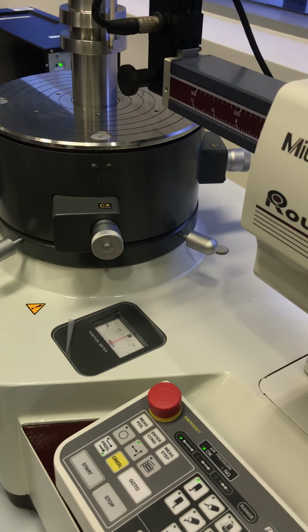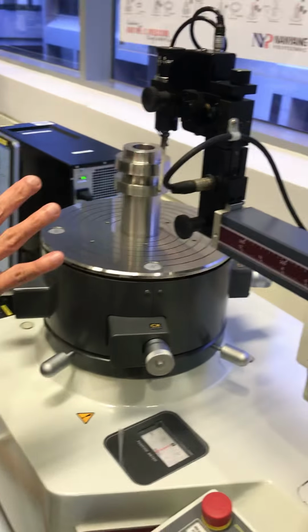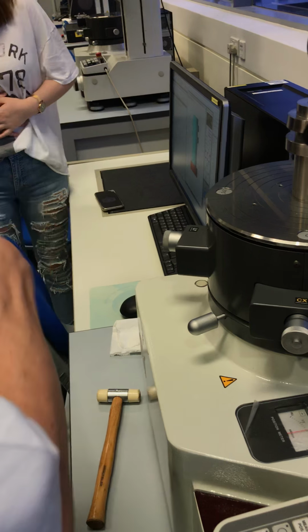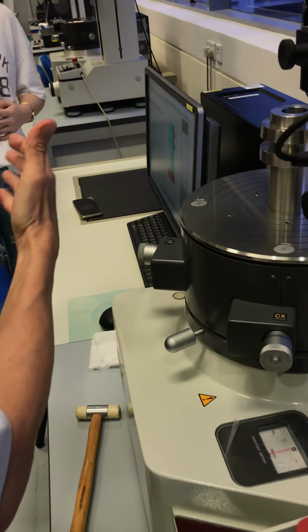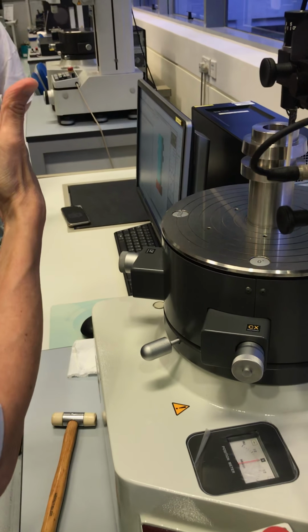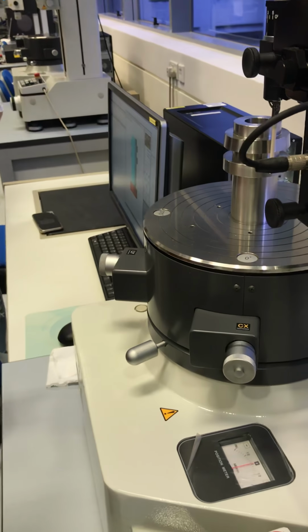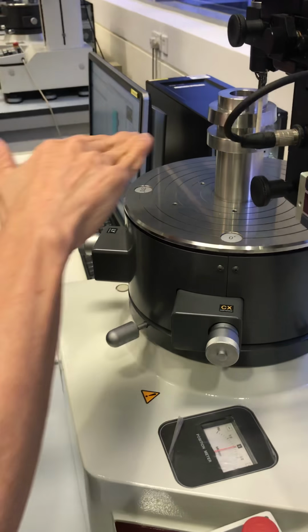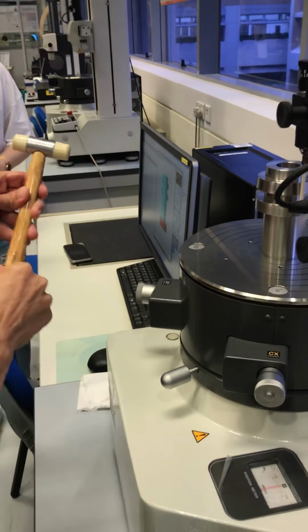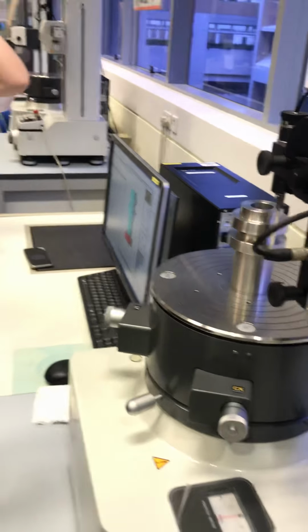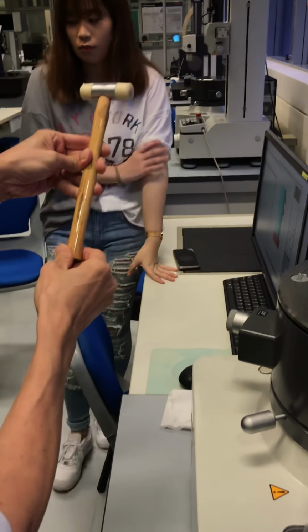Okay, this rough alignment, this is called a rough alignment. Then for very fine alignment at higher magnification, you need the software to help you do the alignment. The alignment is also based on the tilting. We only check the circle, but only one section. But the axis can be tilted this way or that way, right? Your workpiece is so tall, so you might be tilting this way or that way.